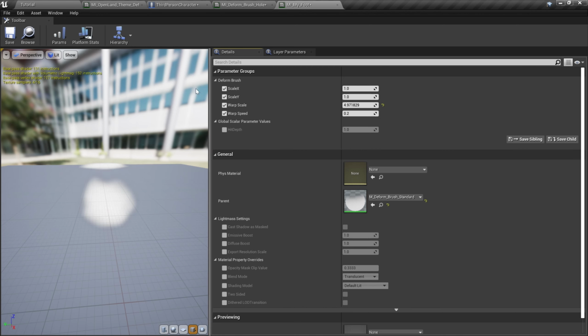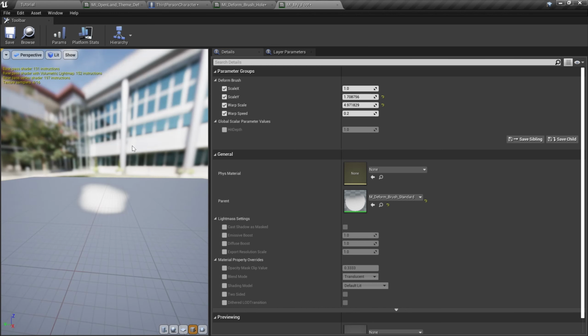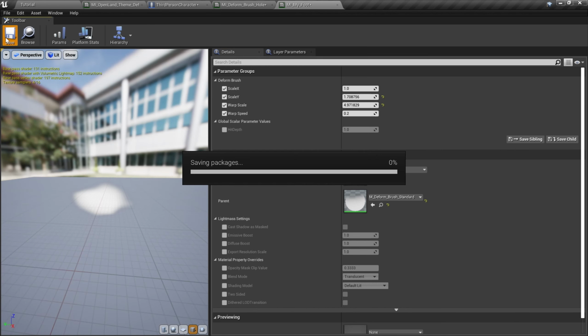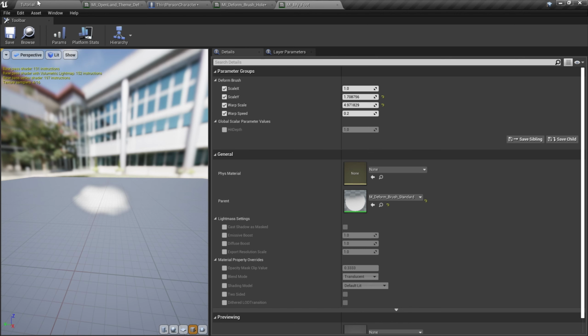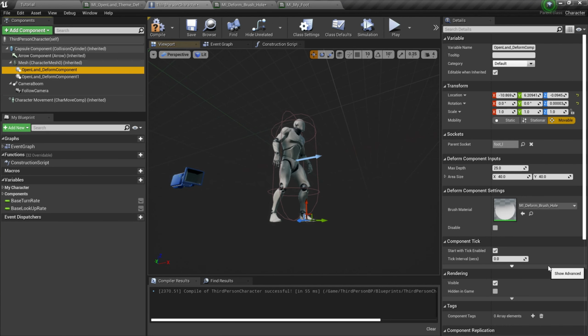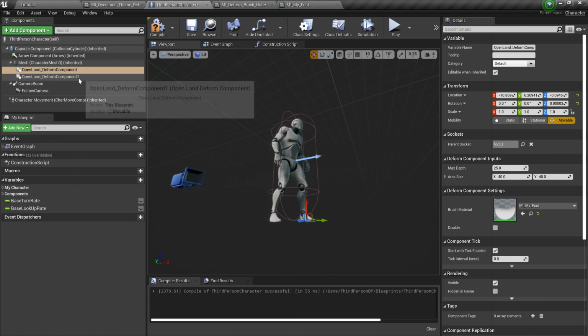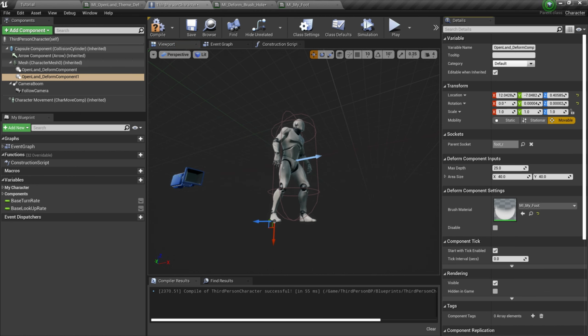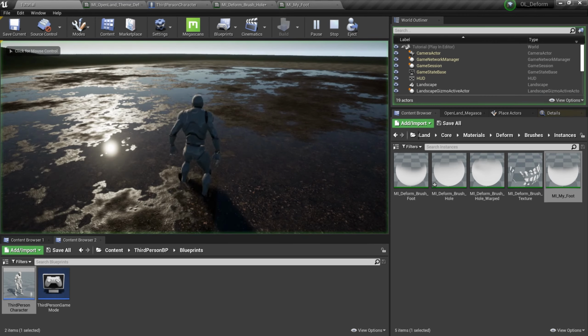And then you can scale this material for footpath, and I think we can simply reduce the Y scale like this. All right. I think this is just fine as a footpath, and I'm gonna save this, and I'm gonna use this my foot as our hole material. Right, and I'm gonna select this, go to my character blueprint and select my component. I'm gonna hit this arrow icon and select our new material, and I'm gonna do the same thing for the other component. Right, and I'm gonna compile and save this. Right, now let's try to play our game.